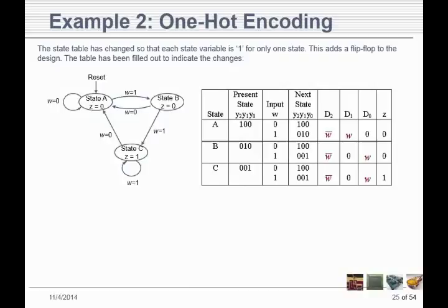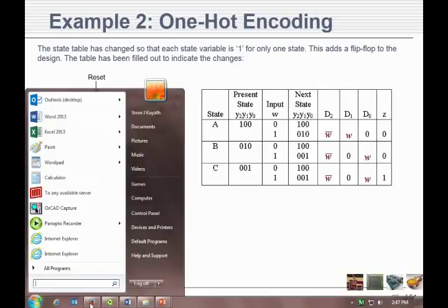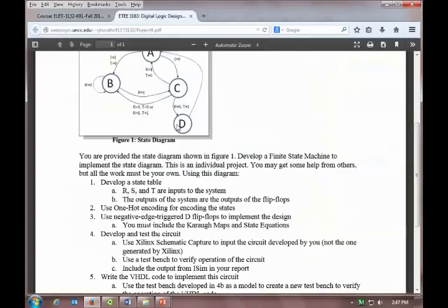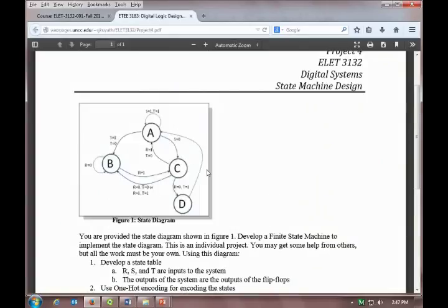And I made that a little complex because there's 3 input variables. Don't let that bother you. I know that's easy for me to say, but just look at these are ANDed. When I've got them like this, S equals 1, comma T equals 1. That's an AND situation. Both of those have to be true.